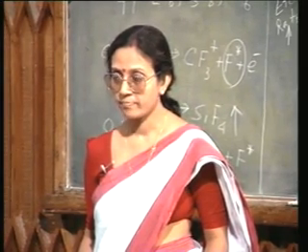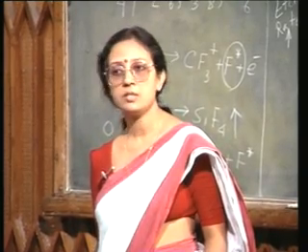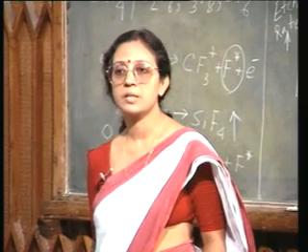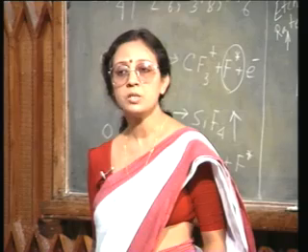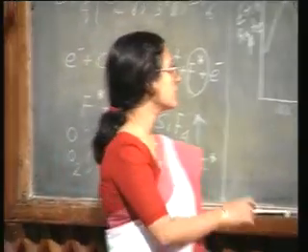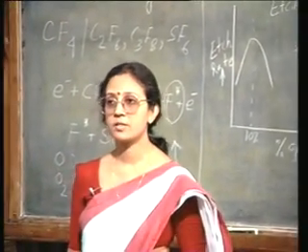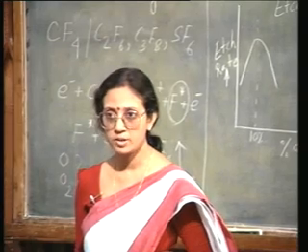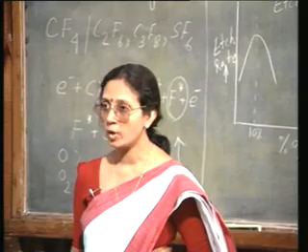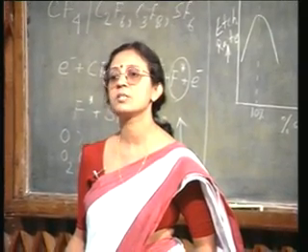Okay. How can we improve the etch rate of silicon dioxide? One possibility is again by putting a small amount of oxygen, just as in the previous case. You will have extra generation of active fluorine species and that will etch silicon dioxide. The problem is, in this process I cannot get any selectivity over silicon.